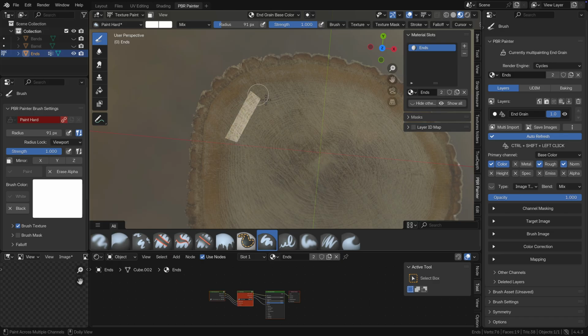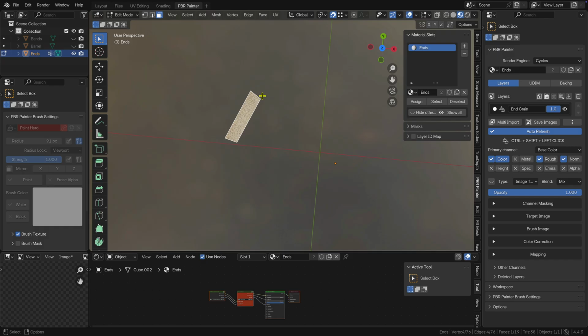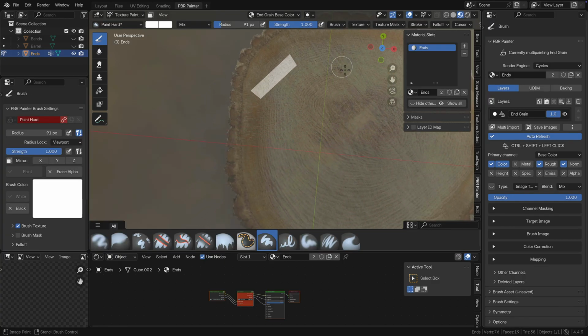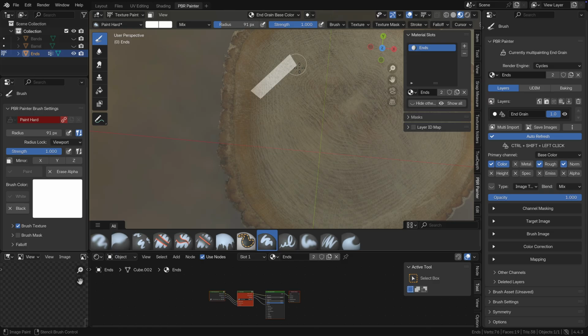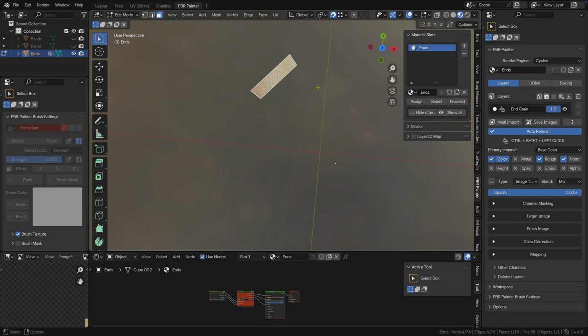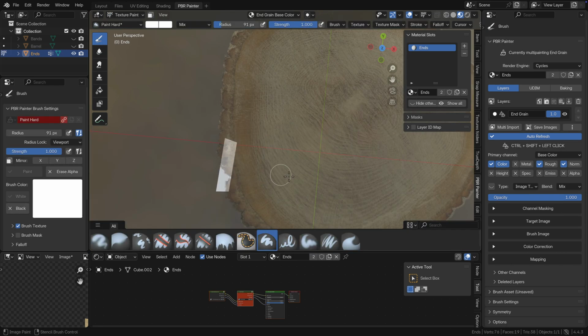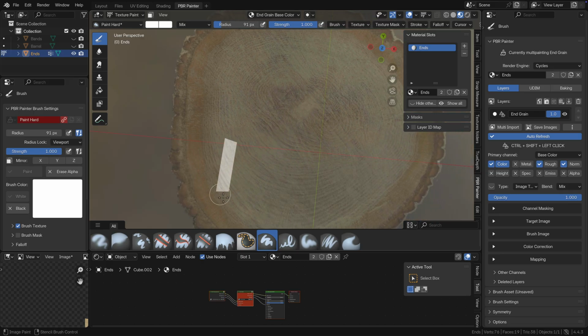Note the difference between the multi-channel texturing workflow we used in the previous video and the multi-channel painting workflow. With multi-channel texturing, the texture is stationary, and one positions the faces of the model. With multi-channel painting, one can move either the faces of the model or the texture, or both. This adds a great deal of flexibility to texturing because you can move, scale, and rotate as you work.